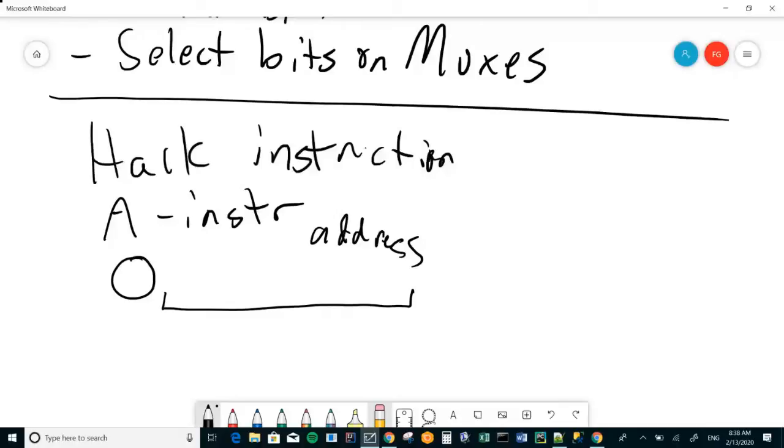This is a really important subtlety in instruction set design. Whenever somebody's marketing a computer, they say, well, its cycle time is 3 gigahertz. But now you can also ask the question by examining the instruction set, how much work is it getting done in a clock cycle? And that too tells you something about the throughput of the device. Certainly knowing the clock cycle tells you one thing.